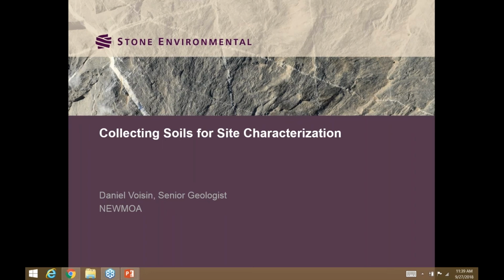He came up with Walther's law, or the law of facies, which you can read for yourself, but it basically describes that in a depositional environment, you have sections of sediments that are laying in series, and over both a horizontal distribution of a site and vertically, you're going to encounter those facies as you're doing your work. So you might have coarse sands 20 feet that way. It doesn't mean that they're just there. They could be right under your feet. And so that variability is accounted for in Walther's law.